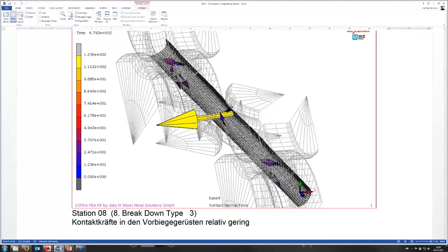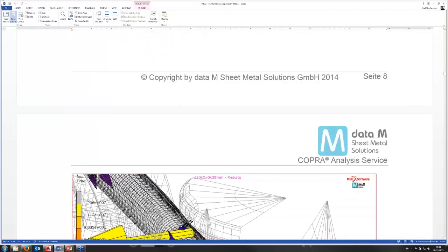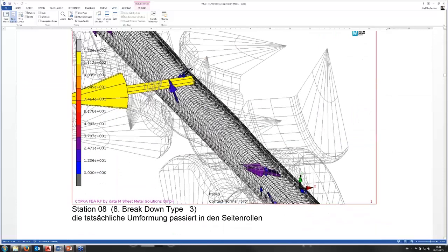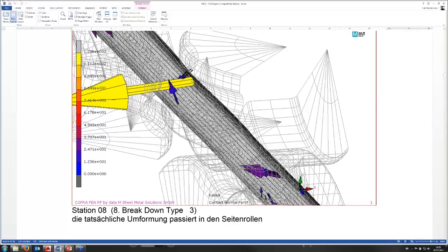Some forming forces here at this particular area. Because the material didn't bend or assume the geometry we would like, we now have to imagine that the idler rolls are also doing additional work to give the material its correct position, because they're now fighting against material that hasn't been bent as we would have desired.